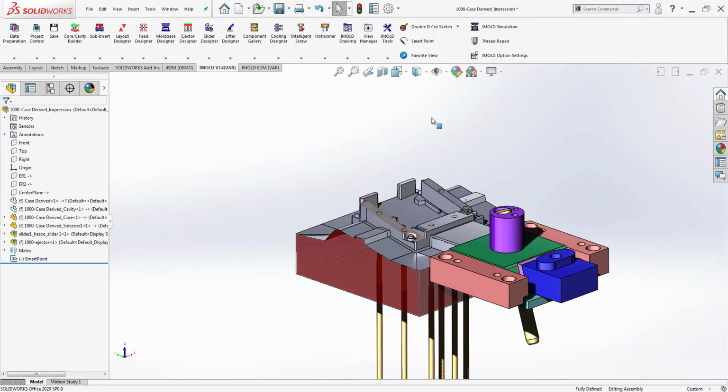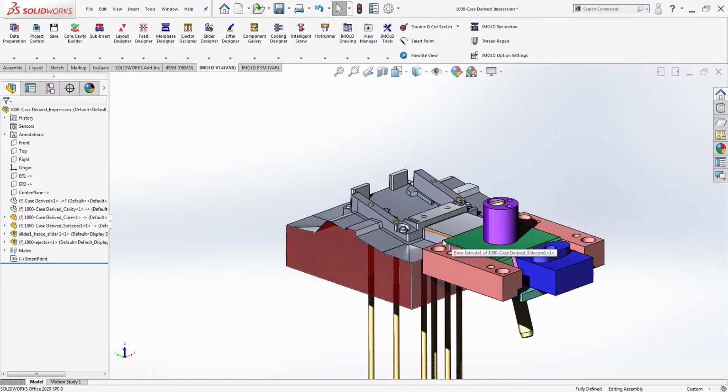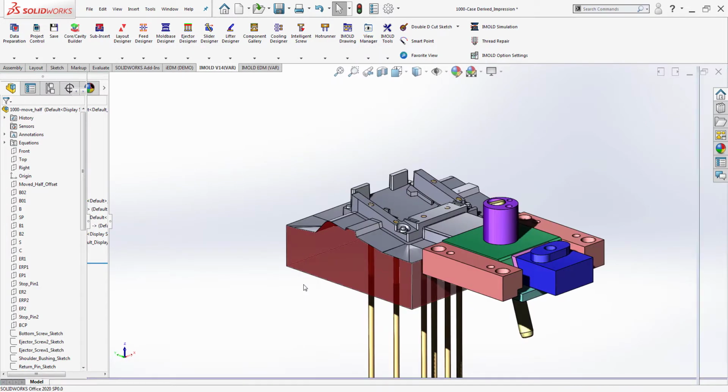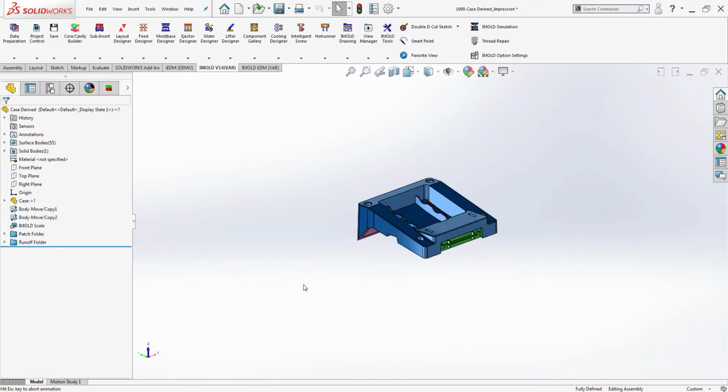From the View Manager, hide the product and cavity insert to have a closer look at the ejector pins trimmed. If you noticed, 4 of the 6 ejector pins are on a featured surface. They have to be keyed to prevent them from rotating. We can add these keys by modifying the ejector pins.